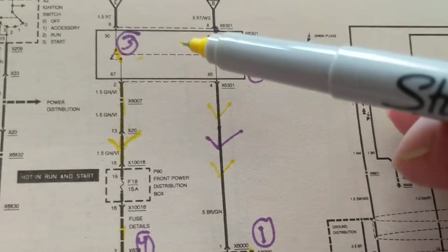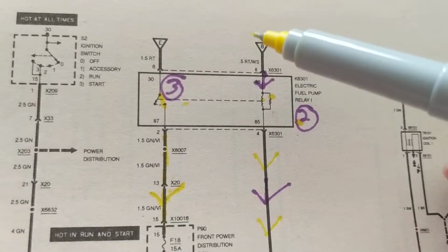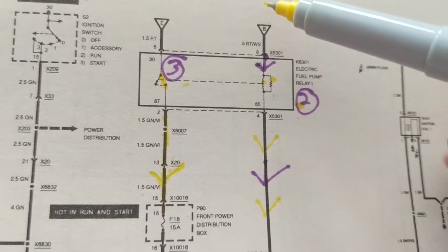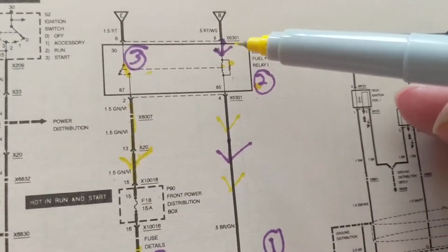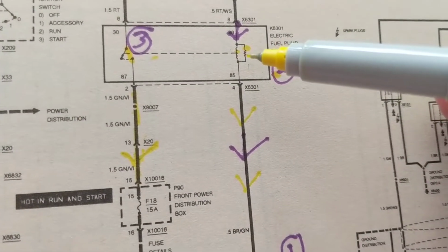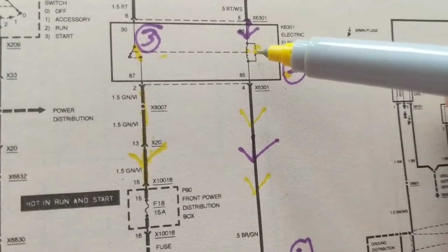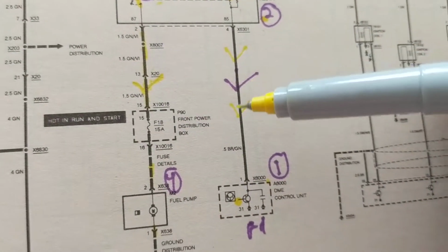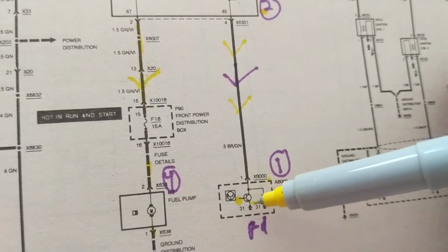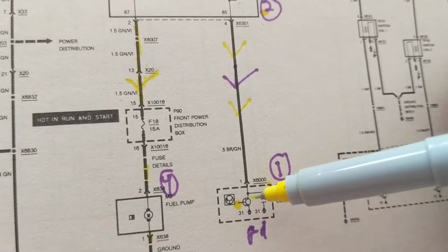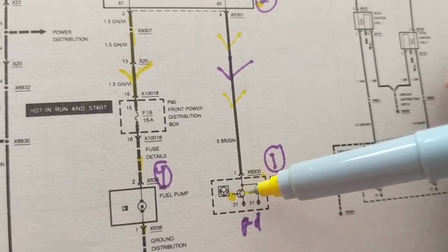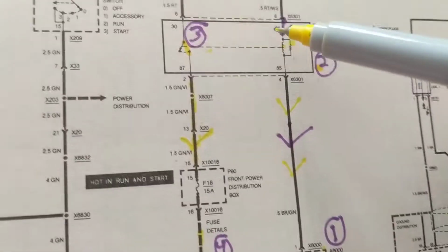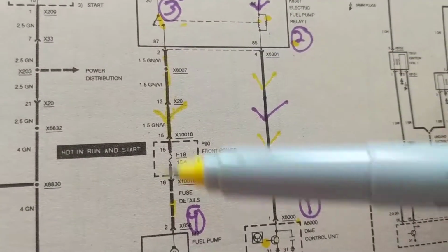So therefore, reading a schematic, as we said, you usually start at the top. But since I know the symbol of a relay, I know something has to turn this part on first. And looking at the diagram, at the symbols around it, I say, okay, this has to give me a ground. This is like a short circuit when it works, knowing how a transistor works. So first you have to know how the symbols work. Then you can figure out how to read the diagram.